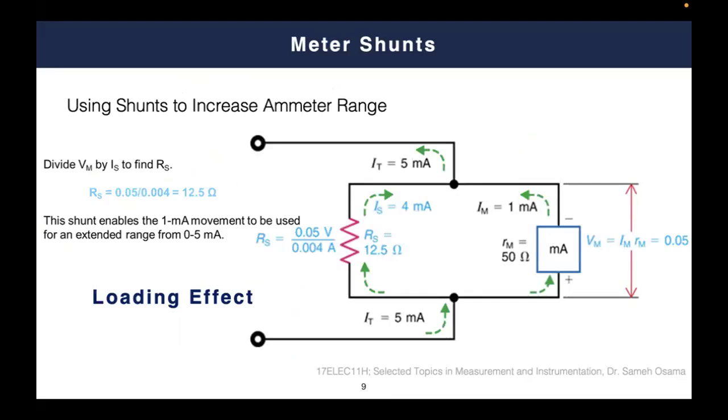It simply impacts the current. Because as you know, when you add the resistance in parallel, the current is branching, because you have a current flowing in the meter and a current flowing in the shunt resistance. So a parallel or shunt resistance model here will not work, because you don't want to increase the current. You need to increase the voltage.